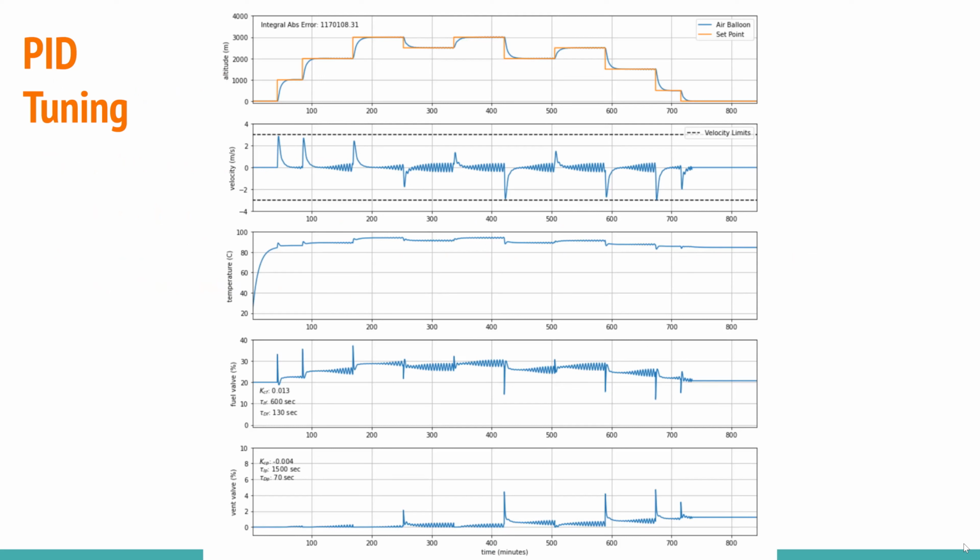Here is an example of one of the PID controller simulations. We took the FOPDT parameters that we received from the regression, put them into IMC tuning correlations, and then further tuned those parameters to decrease the integral absolute error to develop the best performing controller.